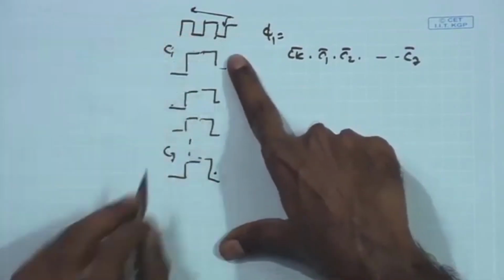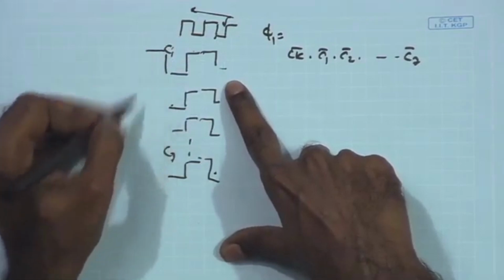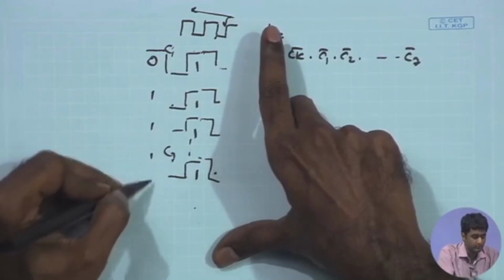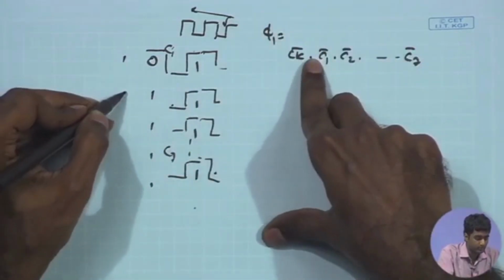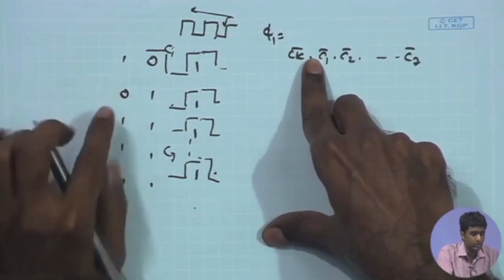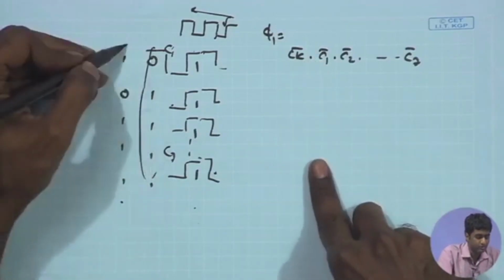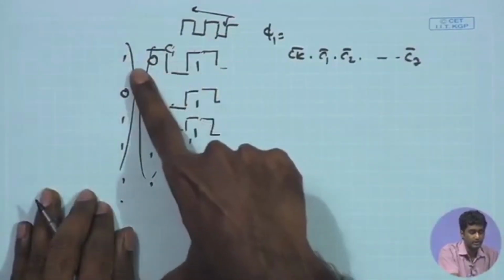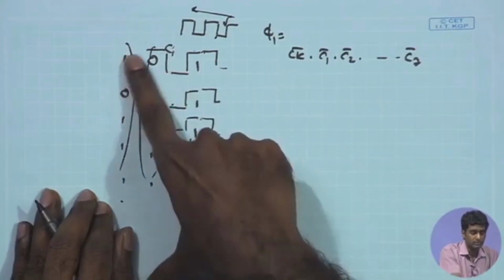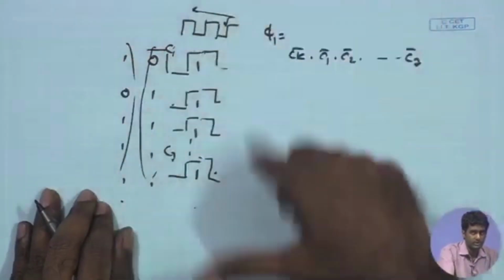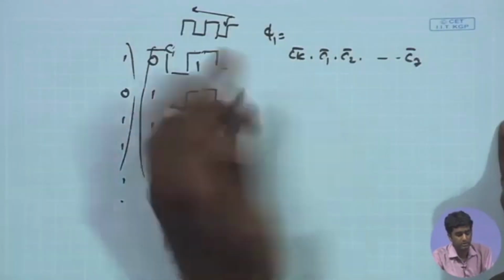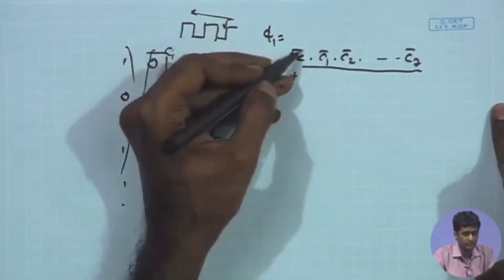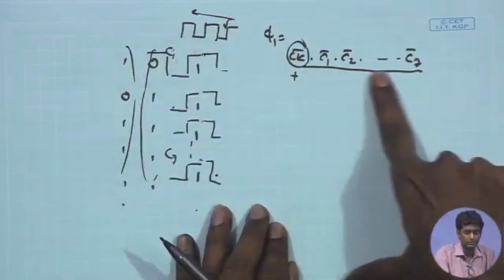That is what we discussed, and for that the only thing you need to do is apply more logic, for more counts, like here I am talking about 1 1 1 1 all ones. Before that you will have 0 1 1 1 1, before that you may have 1 0 1 1 1 1 and so on. So, I will apply the logic corresponding to this combination, and set them all to 0. Whenever these particular phases are coming for the counter, I would like to keep, for this entire duration, the phi 1 high. So, I can just use that additional logic. So, basically it will have another OR gate, another OR gate. So, if you get the first combination over here, I may not even use CK in that case. I will just use the count C1, C2, C7 bar.